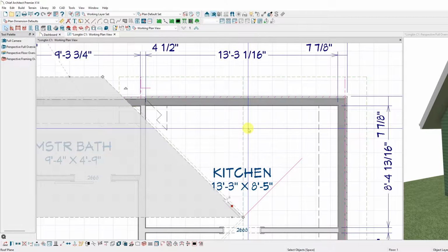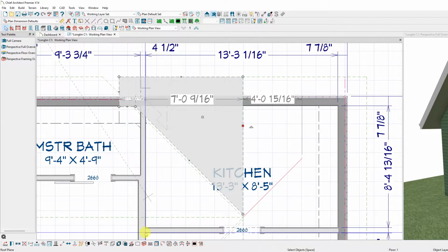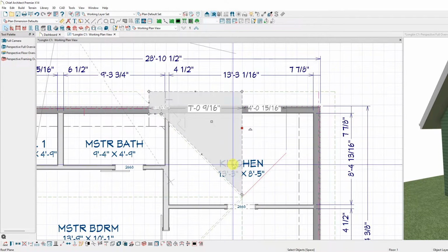So what I ended up doing was going into that line specification and turning it to 90 degrees instead of 90 point, it was like 5 or 6 digits after that. So it was barely off by some little piece, and that's what's giving me the fishing pole out the back. Once I got that straightened out, I couldn't get them to join, but all that took was pulling them a little further apart. One of them was probably beyond center. So I pulled them both further apart, joined them up, and that's what we got.